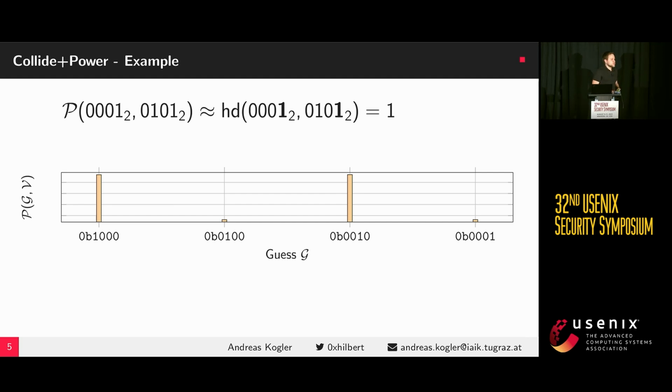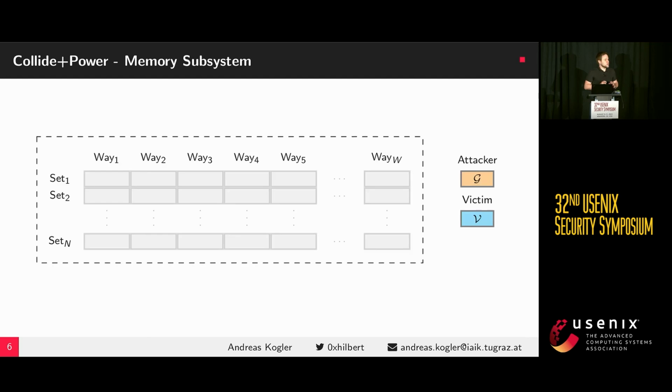So you might be wondering, this is super abstract, a high-level example. Where do we find Hamming distance leakage in a CPU? And the good or bad answer, depending on who you ask, is basically nearly everywhere. Every time we have a shared component, we observe some sort of Hamming distance leakage. And you might have seen some similar diagrams in the past 2 days.